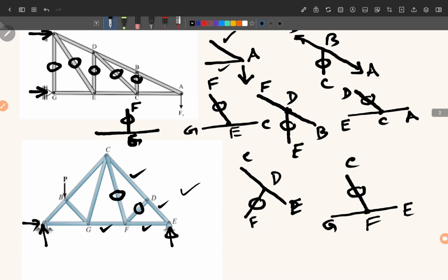And if we go to joint G, there are four forces. This cannot be applied. Similarly, at joint C, there are three forces, but two of them are not in a straight line. Similarly, B has how many? B has 1, 2, 3, 4. Okay, so we cannot say anything about the forces at B, G and A.